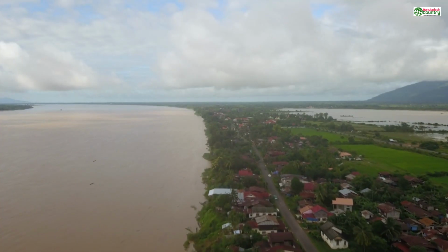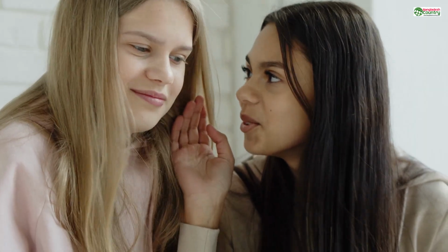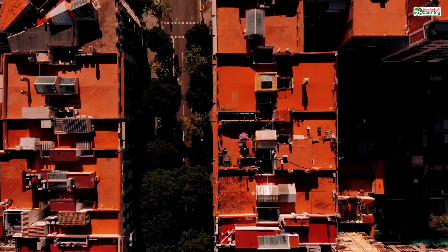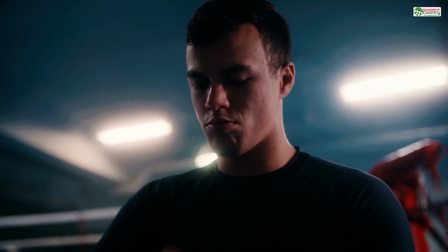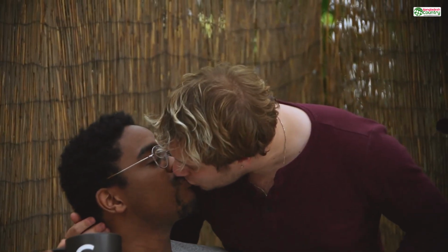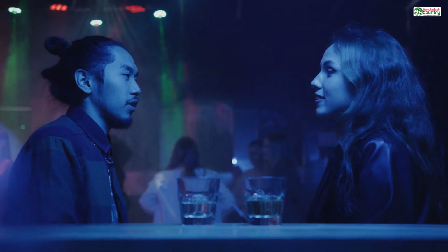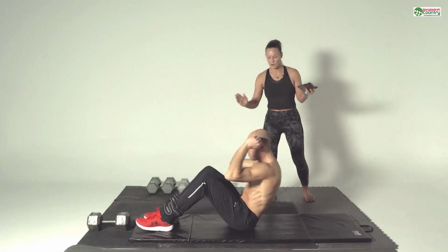So now you understand the secret. It's not about just making a 3D shape. It's about being clever with its internal geometry. You've hollowed it out, you've determined the perfect wall thickness based on the material's datasheet. You've cleverly placed your escape holes on a hidden surface, and maybe you've even added an internal lattice for uncompromising strength. Your file is now lean, efficient, strong, and printable. You've transformed that $200 quote into a $20 reality. You've solved the problem of volume.